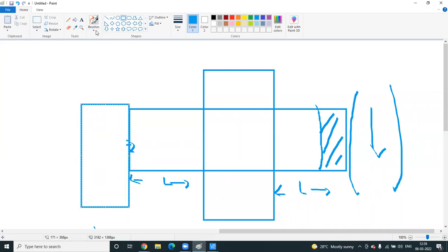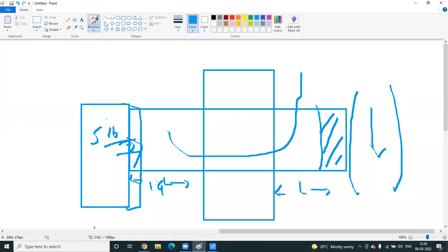Oxide layer can give you a force. This is the force, the stress effect will come. So about 2 micrometer is reduced to 1.9 micrometer. So 1.9 micrometer is passing the current, it will take only 1.9 micrometer, but you designed this circuit for 2 micrometer. So what will happen? This is the damage. Damage means EM also will occur, many effects will occur here.